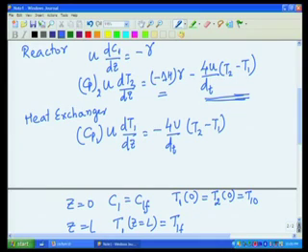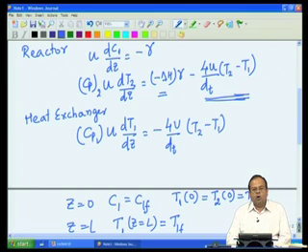Why coupled boundary condition? Because typically if you have a differential equation and you know all the boundary conditions at one point, namely let us say the entry of the reactor, which is what typically happens when you have a single pass reactor or a normal tubular reactor. But in this particular case, we have a tubular reactor, all right, but we need 3 boundary conditions, and we do not know them all at the inlet or the exit point; we know some at the inlet point and some at the exit point.